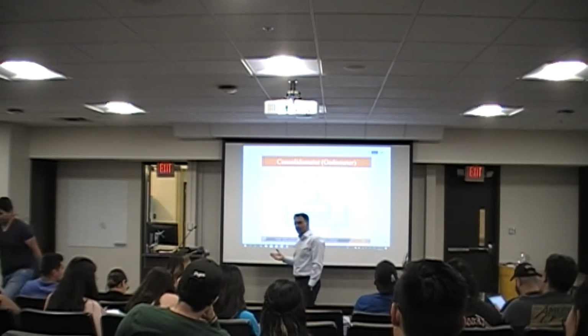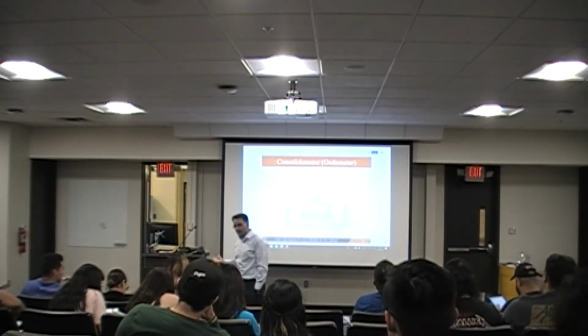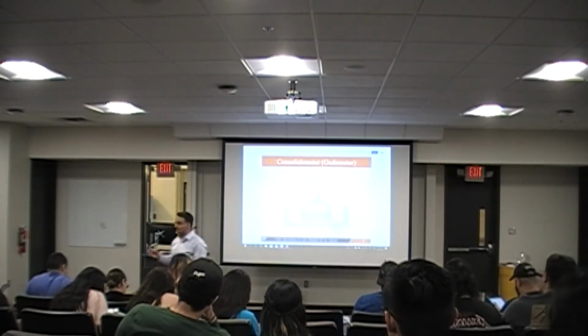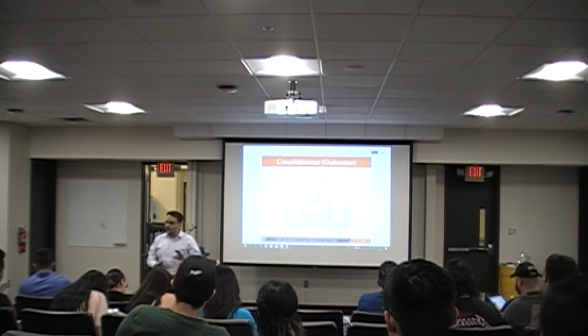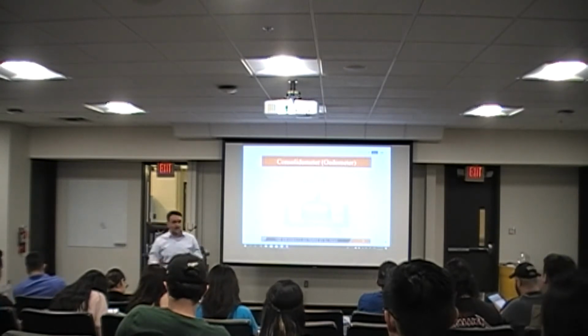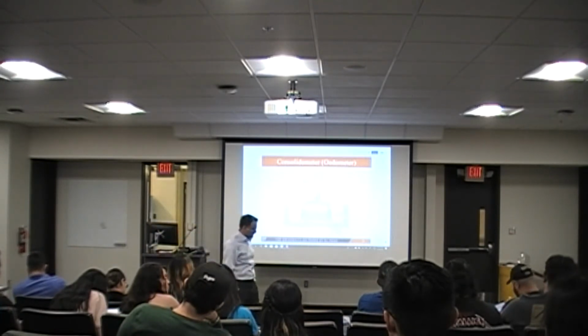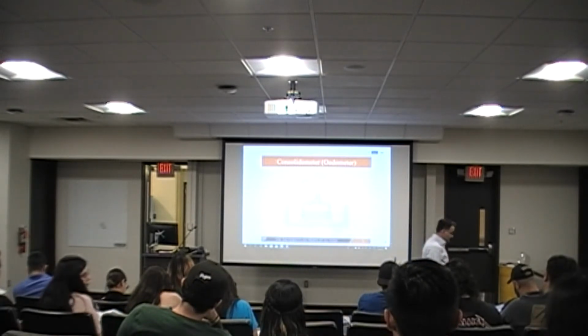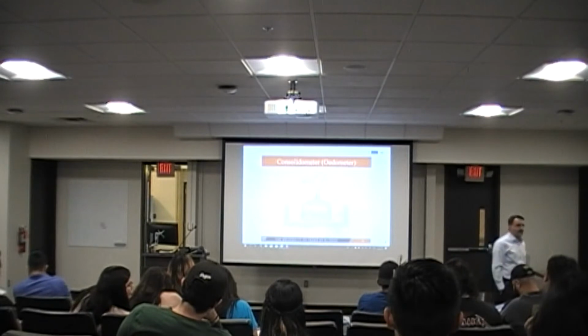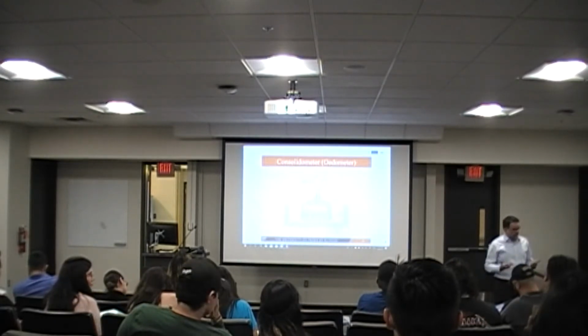But the second component that we had, the time dependency of the settlement, is the one that is somewhat challenging, meaning that you have to figure out multiple parameters from different types of tests to be able to calculate the time-dependent settlement. All right, so time dependency of the settlement has to do with drainage, right?